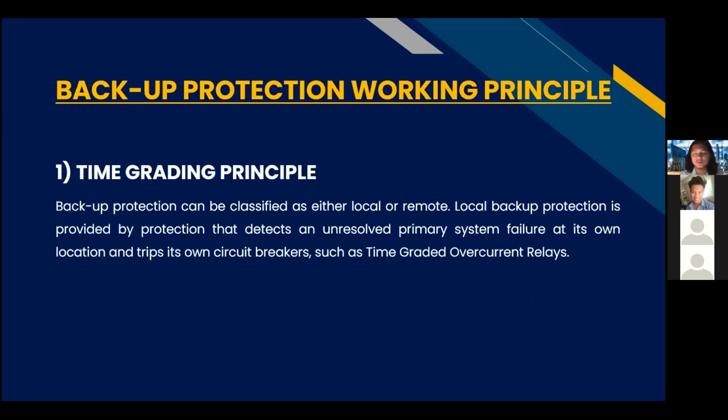Next is the working principle of backup protection. Backup protection works in two different ways. The first one is the time grading principle, and the second one is the backup protection by duplication. Backup protection can be classified as either local or remote. Local backup protection is provided by protection that detects an unresolved primary system failure at its own location and trips its own circuit breakers, such as time-graded overcurrent relays.